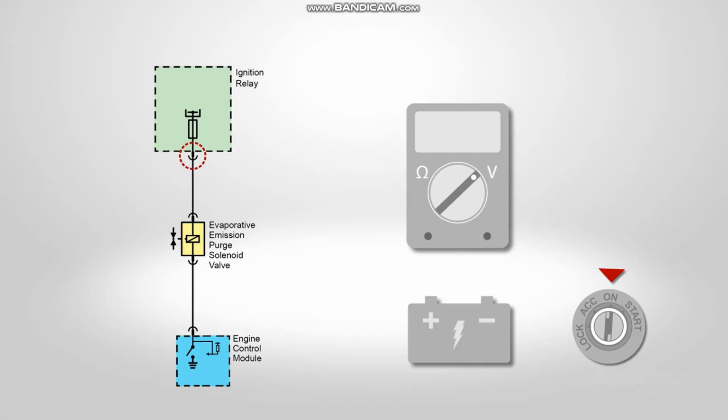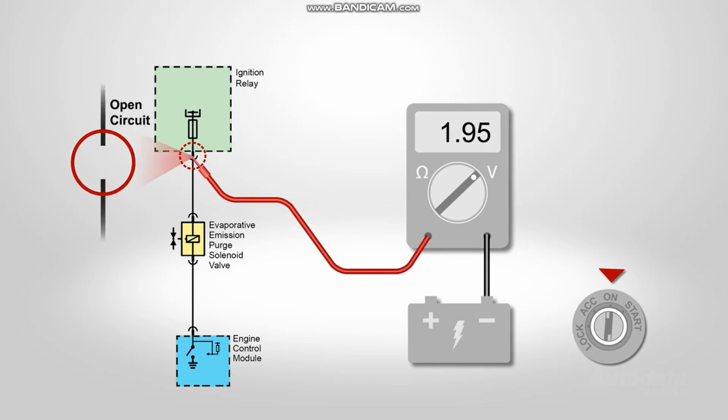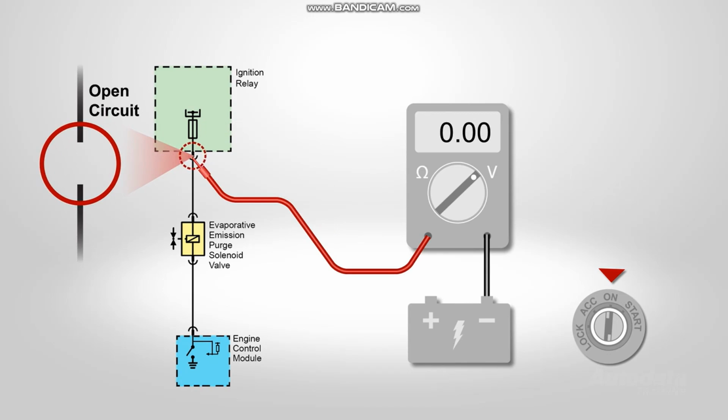If there are any other connectors in the circuit, it will be necessary to locate and test for correct voltage at each one. With a 1 metre lead connected to battery negative, back probe any connectors in the circuit at the correct terminal and note any change in the meter. A correct voltage reading on one side of the connector with no reading on the other will indicate an open in that connector. Systematically testing and confirming will isolate the open to a section of harness.